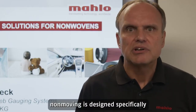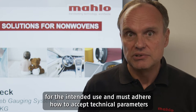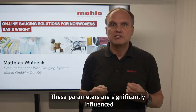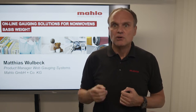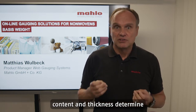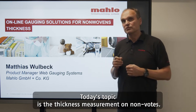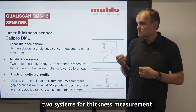Nonwovens are designed specifically for their intended use and must adhere to exact technical parameters to work perfectly in their final destination. These parameters are significantly influenced by the physical properties that result during production. The basis weight, the moisture content, and the thickness determine the decisive properties of the nonwoven. Today's topic is the thickness measurement on nonwovens. MAHLO is offering two systems for the thickness measurement.